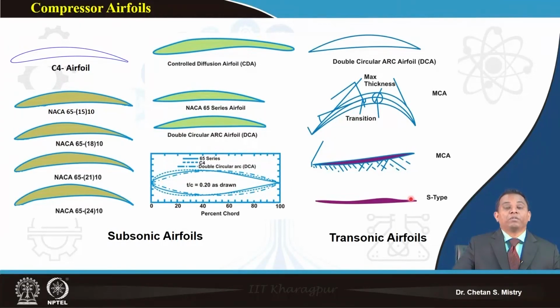They may have flow that is transonic, and in that transonic region they are using this kind of airfoils. The pressure ratio as of today, in multinational engine-making companies, is claimed to have reached around 1.8 to 2.